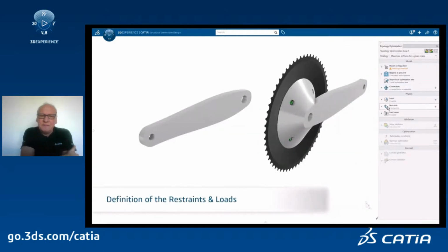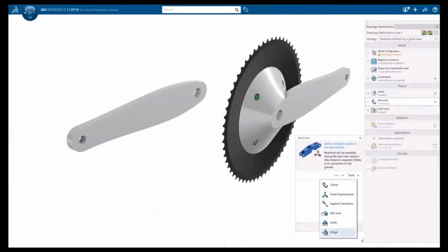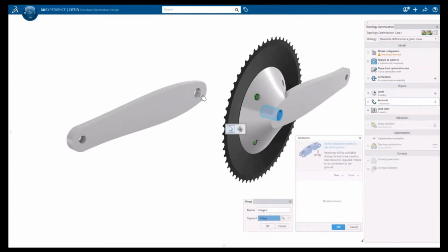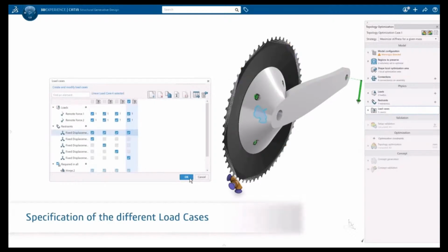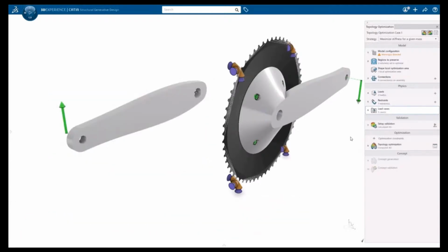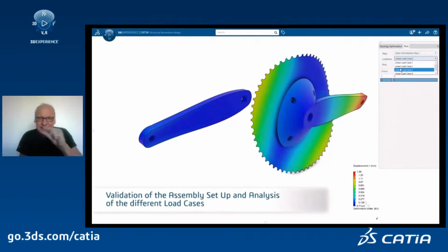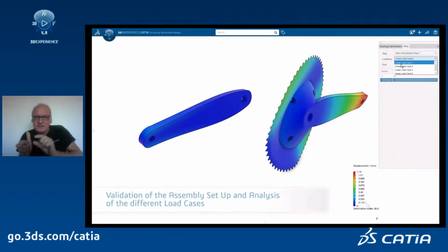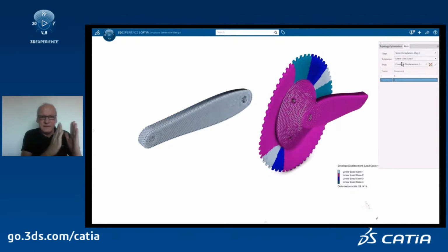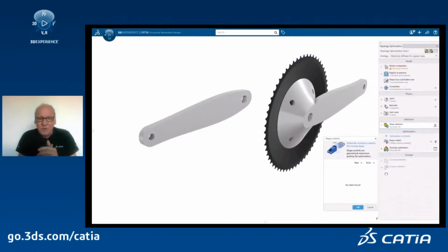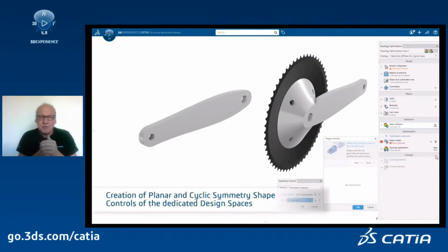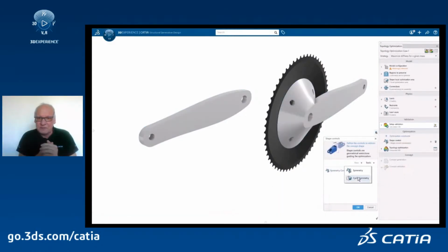And of course, depending on the manufacturing constraints that you select, it will create, for example, some parts for additive manufacturing, some parts for casting, some parts for plastic injection molding. If you are doing a plastic part or casting part, you are also able, for example, to drive the thickness. Most of the time, you try to get a constant thickness. You can also control the dimension of the ribs, the spacing between ribs. So it's really a tool to do any type of part, whatever the manufacturing process you selected to produce the part.